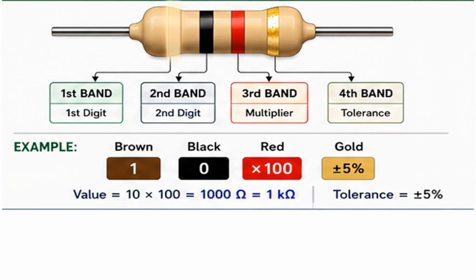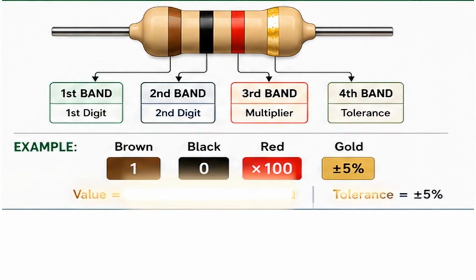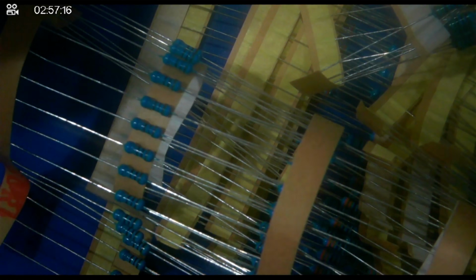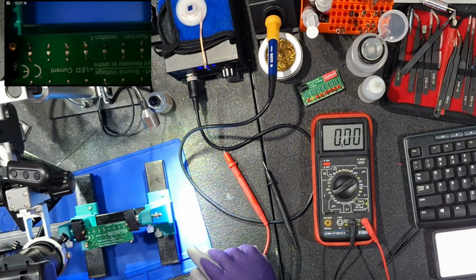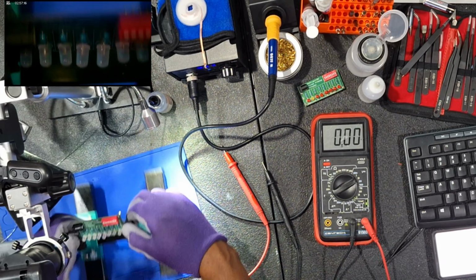But one of the problems I find with it, when you're looking at some of these resistors, is that it's hard to tell which stripe is the tolerance and which side to begin from. Even though the tolerance is normally spaced further from the rest of the bands, sometimes it's hard to tell. So it's not my favorite way to find resistance values.